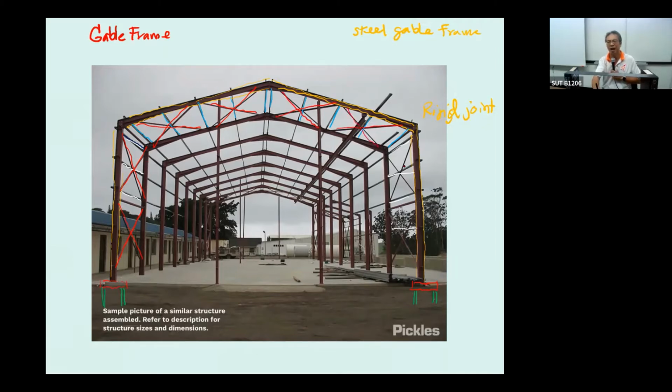And on the design of this frame, you transfer the force from the roof sheet into the purlin, and then the frame will act by the vertical load, the dead load and the live load, and the proper load combination of dead load and live load.